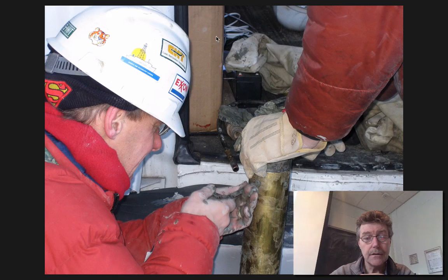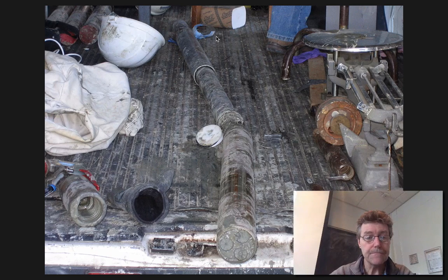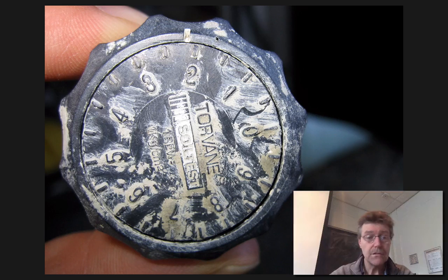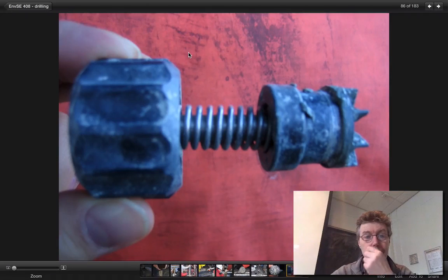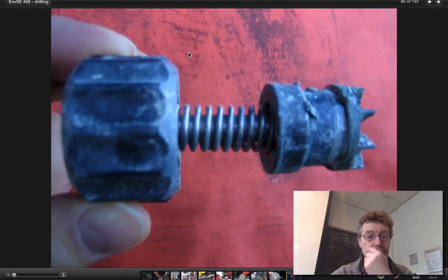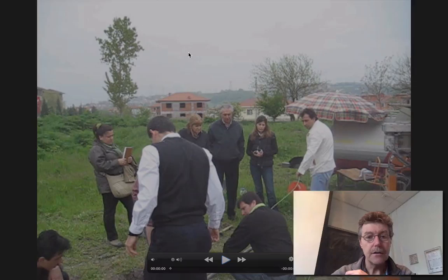Coming off the rig, end of the sample, actually turning the set screws in with an Allen key. They turn in, and this is just what the sheared off sections look like after it's been tested. Decoupled from the tool, the torvane is what it's called, just registers a magnitude. This is the maximum torque that it got before it slipped. Yeah, you see it there. Just very, very simple. A torsion spring that's standardized.